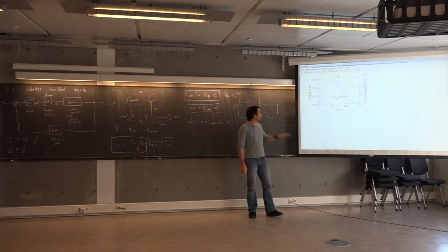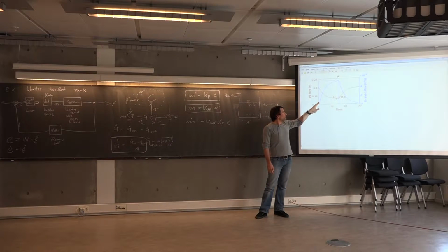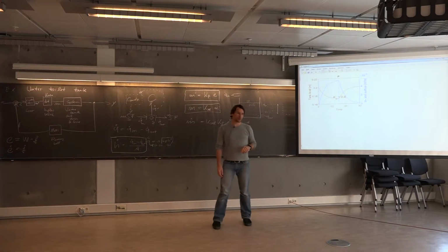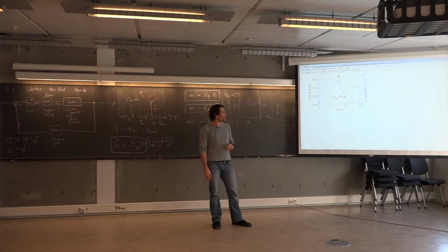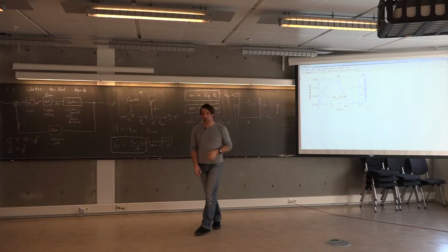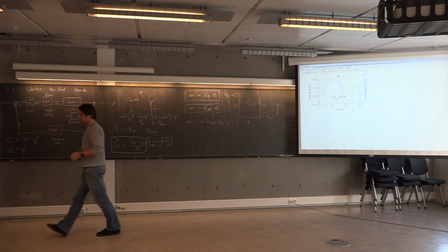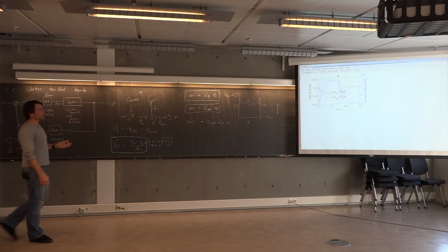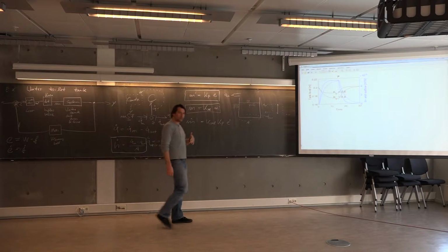As you may remember from the first part, this proportional controller creates a certain offset, which is a not so nice thing with this sort of controller. Obviously, you can play around with this Kp value, meaning, with regards to the toilet water tank example, the ratio of the lever. So if you use another value there, you might be able to actually reduce that offset.